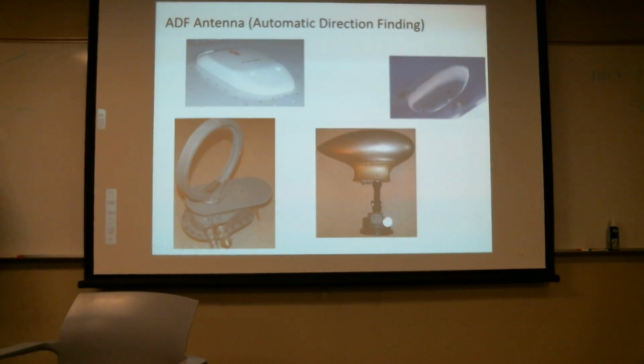This is definitely phased out, but in truth, the system still exists because we have all the AM broadcast stations, right? They all still exist. Did they triangulate with that too, or was it just tuning, like trying to get on a beam, the strongest beam? Well, you would only use it really for triangulating, unless the radio station happened to be pointed right in the right spot for the runway. But you would always triangulate off of two radio stations, get a radial to you, and it's a very rough line to you. Okay, and then cross, and that's about where you are. So it's a precursor to the VOR then? Yes.